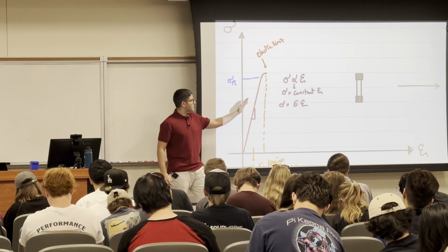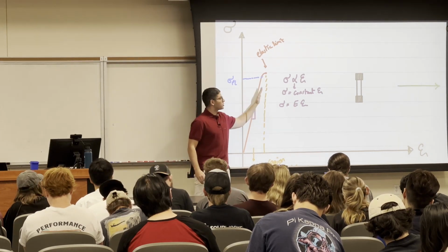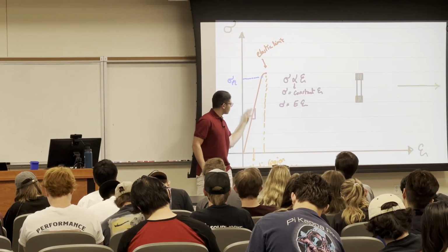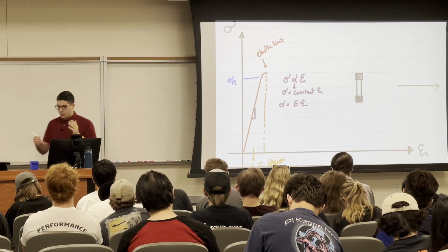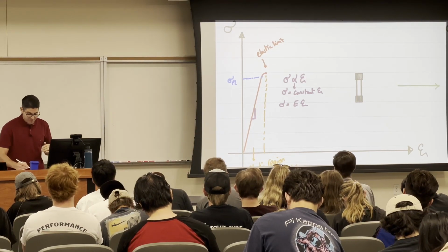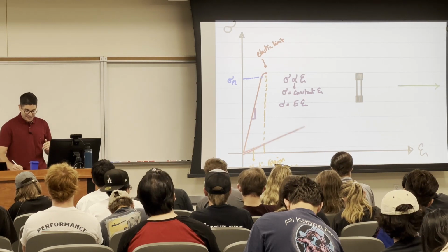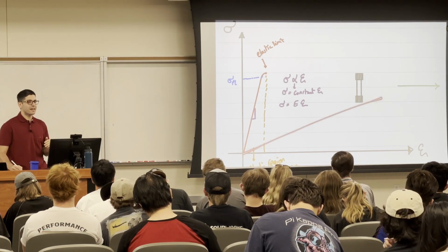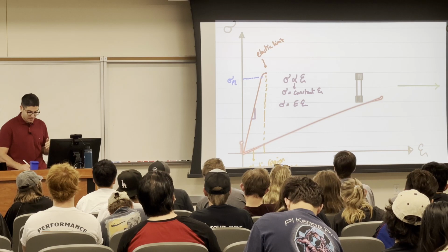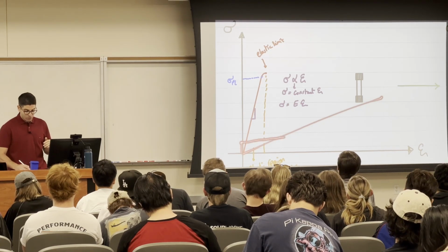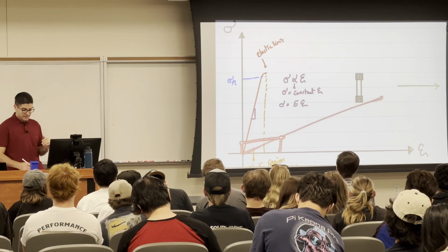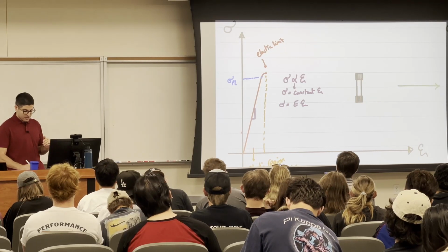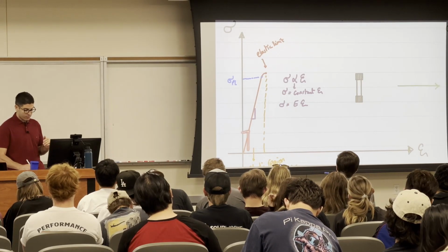And steel, for example, has a high E, so the slope is going to be steep. Let me tell you what the slope means. If I have a material with a shallow slope, that indicates if I apply a stress here, the material is going to deform big time, and you don't want that to happen. Instead, with steel, when I apply stress here, this is the deformation.